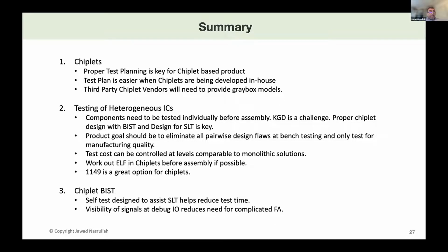I can probably publicly talk about one of them, and that is copper pillar. They are great technology. You try to mold them and reflow them a second time. There are horrible issues with solder bridging and things of that nature. Not that they cannot be worked out, but it becomes a test engineer's challenge. How are you going to find that? You can send them to the FA lab and they will tell you, okay, let's change this, let's change that. But in the long run, these things can potentially come back, right?